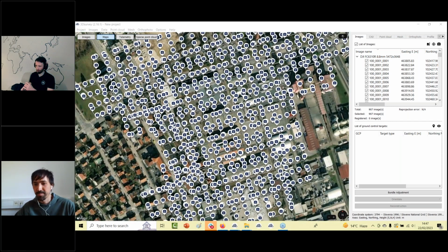As Mattia already mentioned, if you have an RTK drone and the right coordinate system, and if you have ground control points to additionally improve the accuracy of the model, also in the right coordinate system, you can actually use the batch processing and all the steps till the orthophoto are automatically calculated. So it's a super nice trick already inside of 3D Survey for 2 years or something like that.